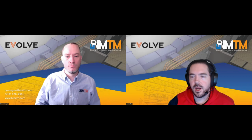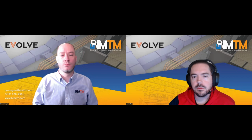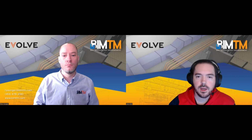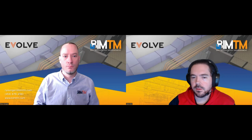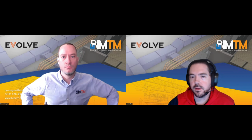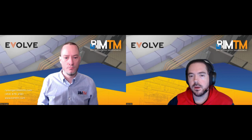On that one, I would say it depends. I know Autodesk has cloud clash detection now. I'm not sure that you would be able to upload a point cloud file to that. What I do know is you can get those point clouds into Navisworks, and you can clash anything in Navisworks. So I would say yes, you can do it. It just might depend on how you go about it.